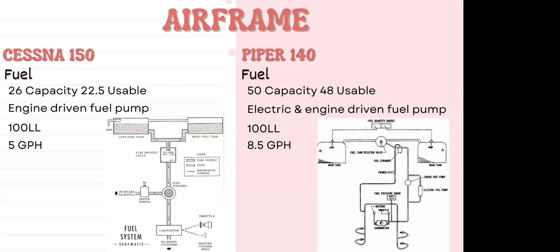Absolutely. So one thing I will say is it is going to depend on the type of 172 you're flying. Do you know kind of what year you're flying? Do you know if it's an older model or a newer model? It's a Mike. Okay. Perfect. So in that case, you are going to have that gravity-fed fuel system, same way, but you are going to have that engine-driven fuel pump. There won't be an electrical fuel pump. They did add that on recent models for that redundancy feature that we were talking about earlier. But it will be attached to your actual engine. And unfortunately, unless you know exactly what you're looking for, it's not going to be easily identifiable.